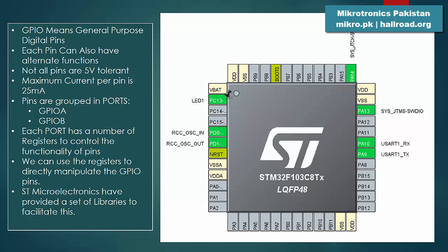So, in order to make it easy, STMicroelectronics have produced a set of libraries called HAL libraries, HAL standing for Hardware Abstraction Layer. These libraries accept commands in simple parameters, and they translate them to those various registers at the lower level, which is abstracted from us and makes the programming easier and more fun. But nevertheless, you can always dive deeper into the registers and access them directly.